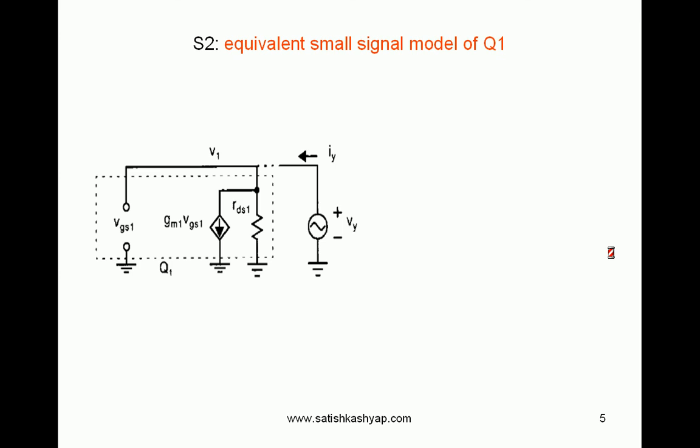So Q1 is diode connected transistor, that is whose gate and drain are going to be shorted. That means it is always in saturation. Under saturation, if you neglect channel length modulation, output current is constant irrespective of output voltage. Output current is constant is nothing but output impedance is infinite. The small signal output impedance is infinite when channel length modulation is neglected.